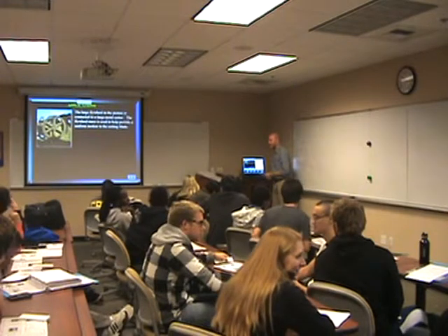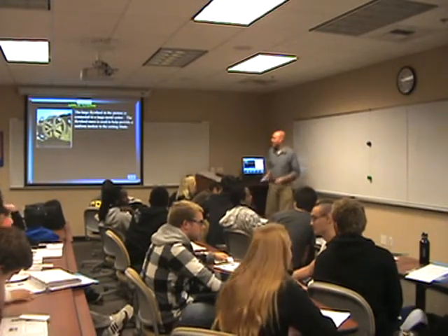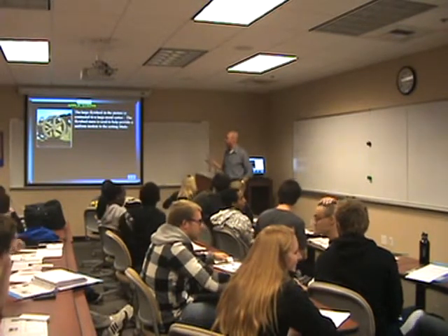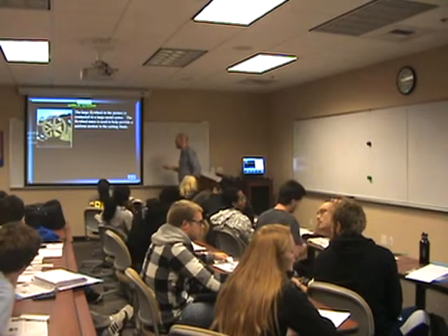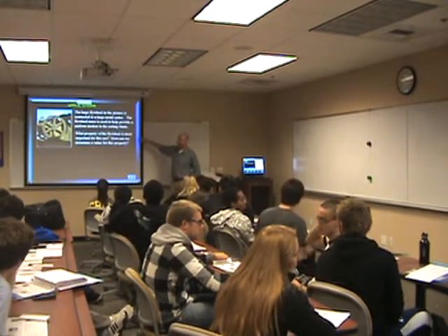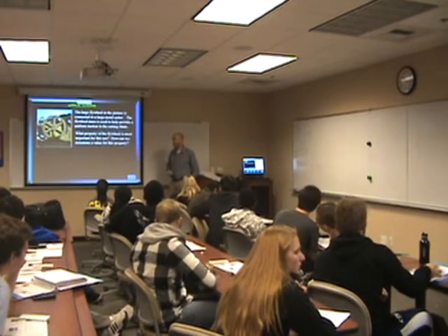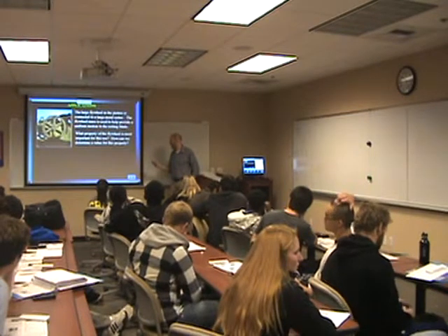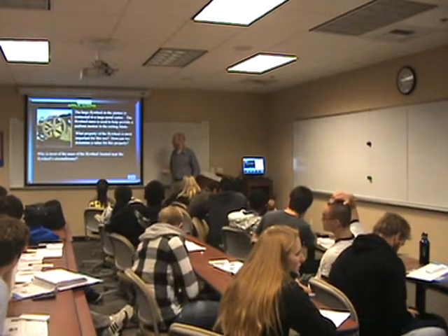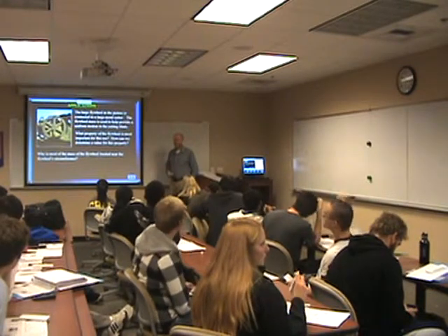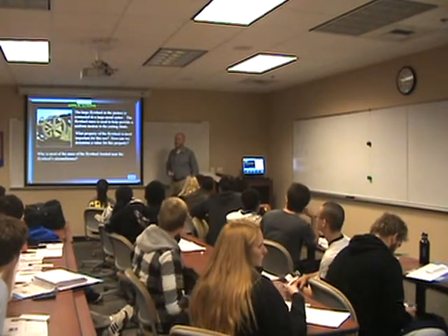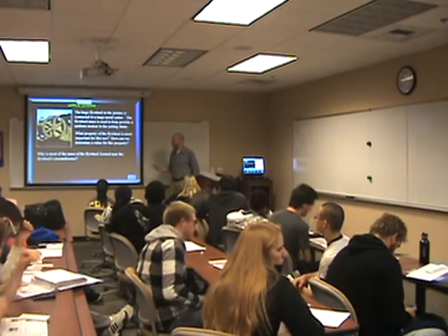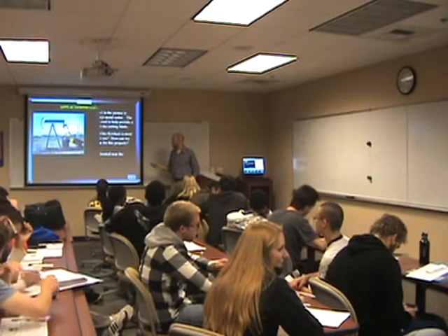So, flywheel. A flywheel is designed such that it has a large radius of gyration, or a large I. What do you want a flywheel to do? Why do you use a flywheel? You want it to keep moving, so you store energy. So we want to figure out, what is I going to be? Why is most of the mass located near the outside edge? So that there is a larger moment of inertia. It's your mass times your distance squared, so we want to put our mass out as far as possible for low-speed flywheels.